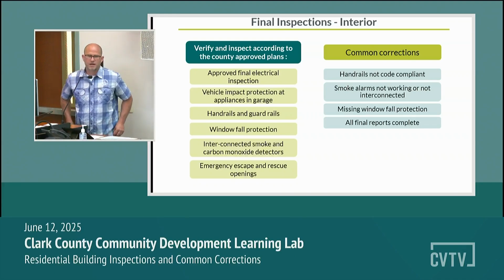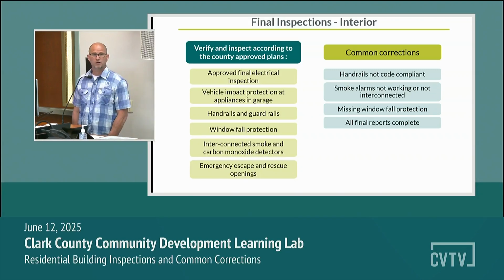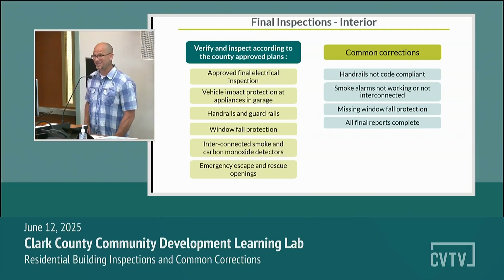For time's sake, we've kind of gone from installation to final inspection. There are a few inspections that will take place in between these two. This county does require a sheetrock nailing inspection. If you have tiled showers, there might be shower pan inspections. Depending on where your house is located, you might have to have a road approach and a sidewalk inspection done. So there are other inspections in between installation and final, but yay, you're at final inspection. Here we go.